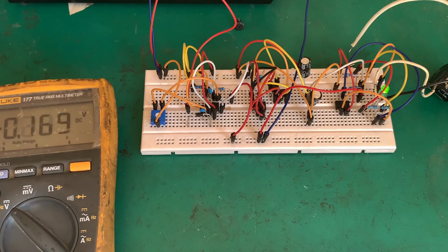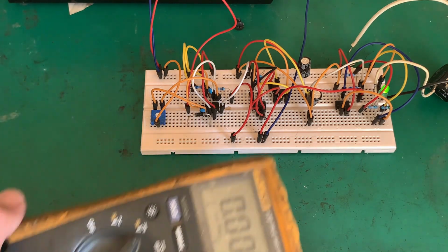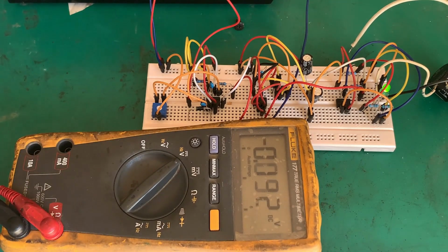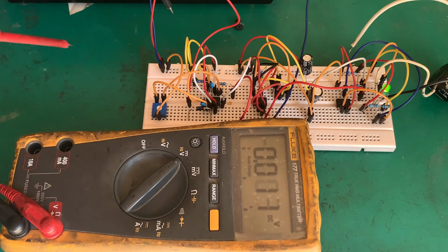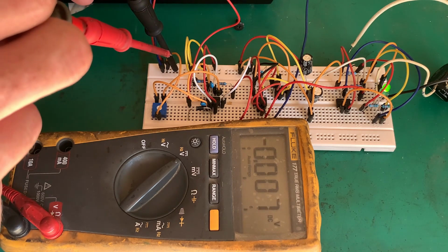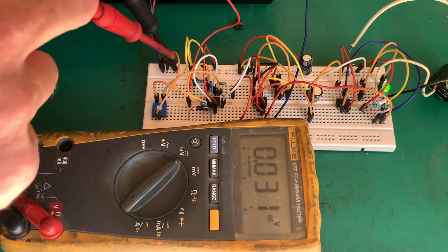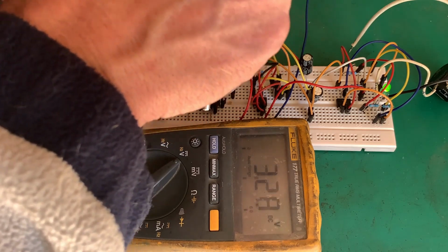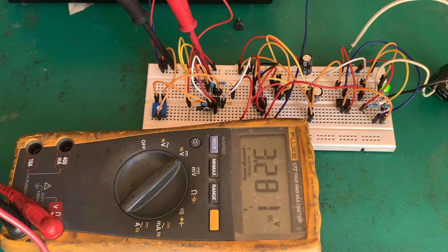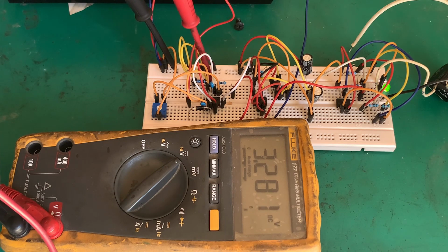Anyway, what I'm going to do is show you a few things on the multimeter. This circuitry over here is referenced to ground. Maybe it'll be better if I put it like that, so if I measure, I'm not in your way. So if I measure to ground, and I measure to our voltage divider pin up here, you can see we're measuring close to, remember the tolerance of the resistors and whatever, 3.2, 3.8.